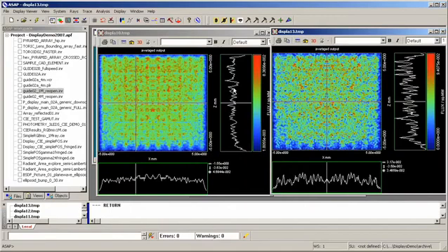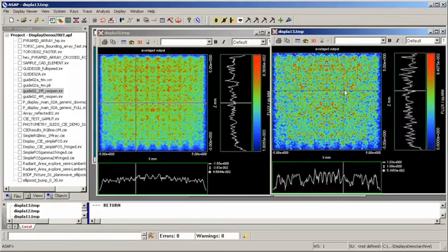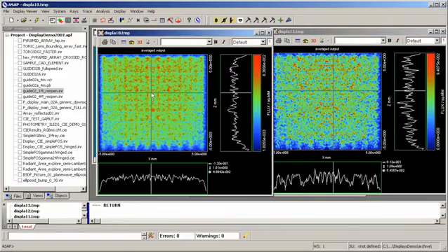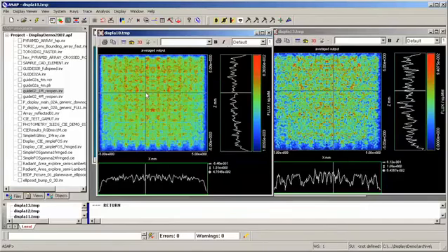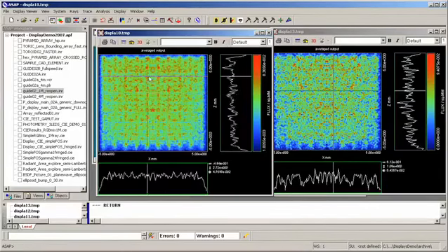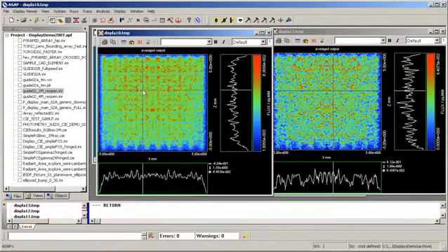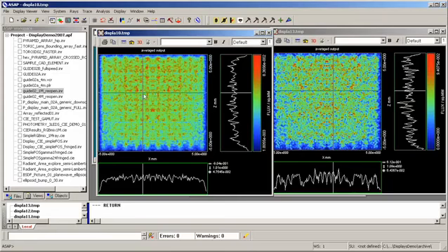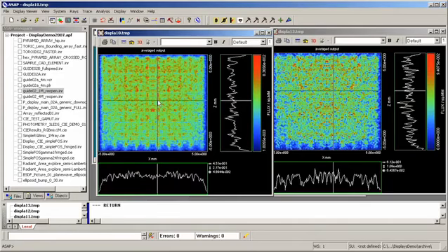And as you see, by looking at the profile of the data for the 4 million rays, we have reduced the noise level considerably. And we're starting to get a real characterization of the irradiance out the top surface. We see definite artifacts from the row structure of the scattering dots. And to some extent, those artifacts are not artifacts, they're a reality in the design. In successive refinements of the design, we would seek to perturb that.